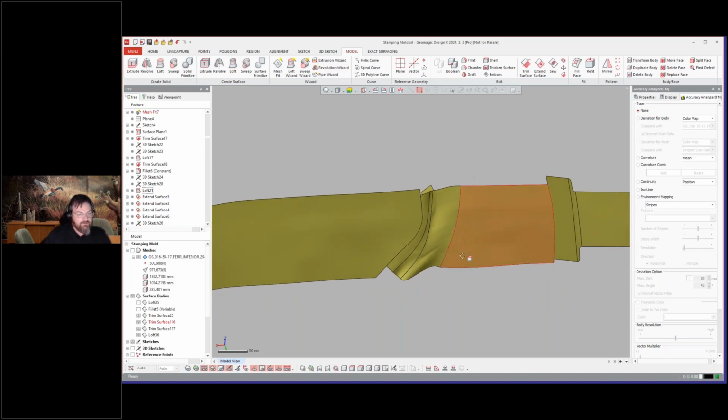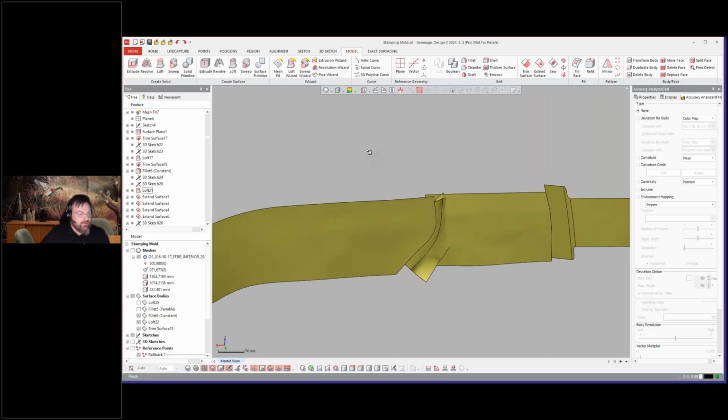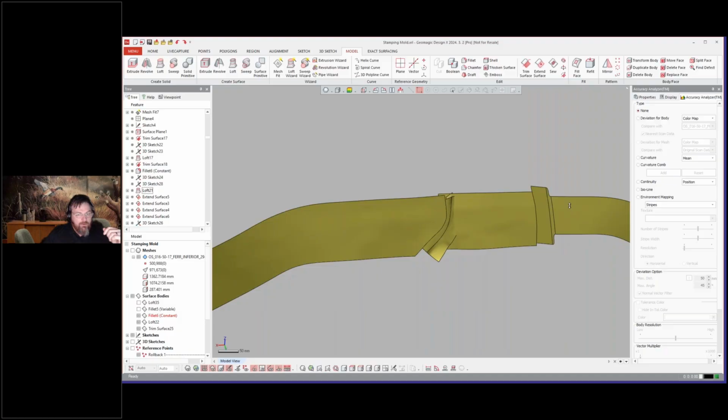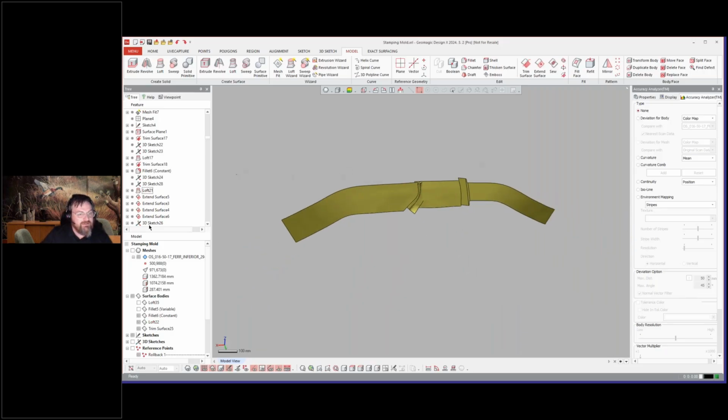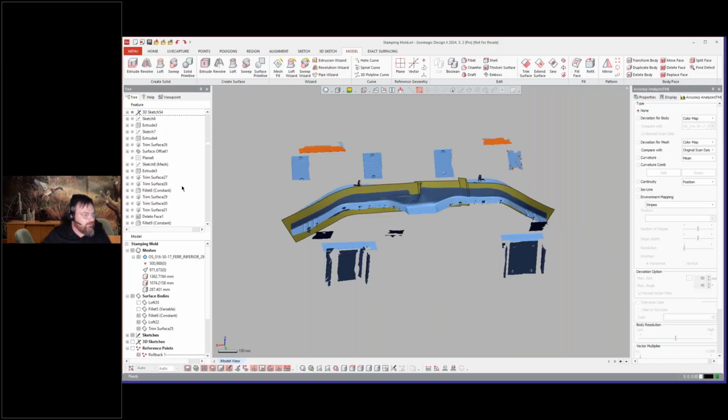And I didn't do the best one, but I'm just trying to show the concept of what we're doing here, and how they're able to trim these together. Sometimes you can fillet two surfaces together, but if you cannot, you do a manual blend like that. And that is a technique that is used a ton in this application right now. So we'll continue with our rolling forward here.